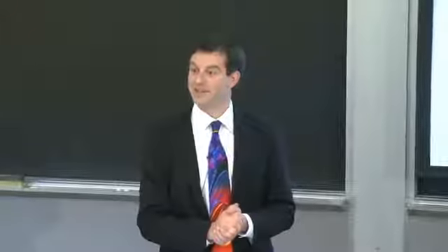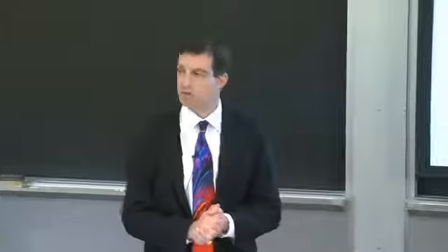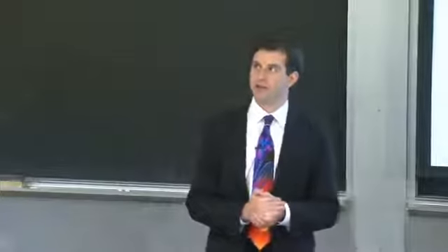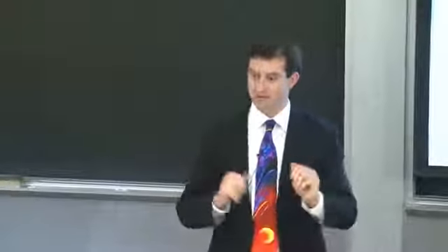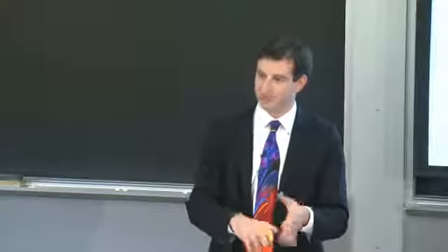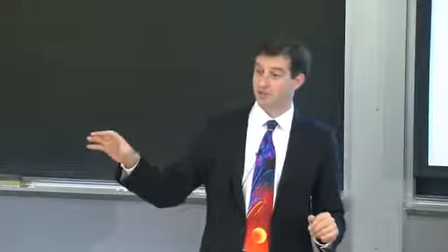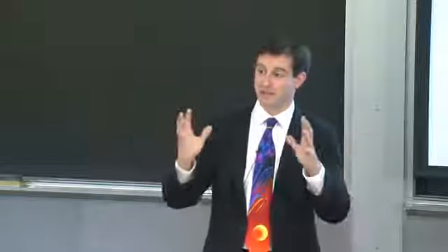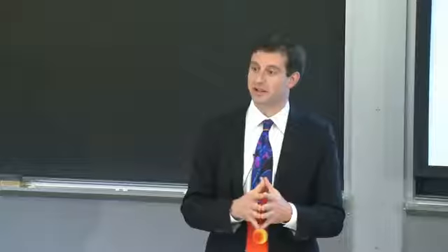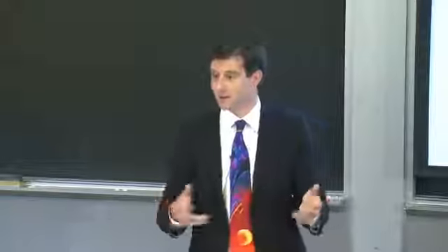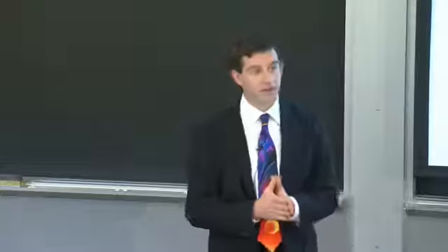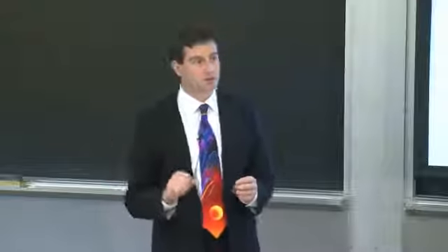How about we start? Oh, go ahead. Yeah. Like performance and performance losses or something. Yeah, okay, so we can describe based on the economic variables, right? Like efficiency, and then within efficiency, JSC, VOC, fill factor, mechanical yield, reliability, right? These are all parameters that can lump into a cost model and ultimately impact the cost, dollars per watt, let's say, of a PV panel. Excellent, so we can describe it based on performance.